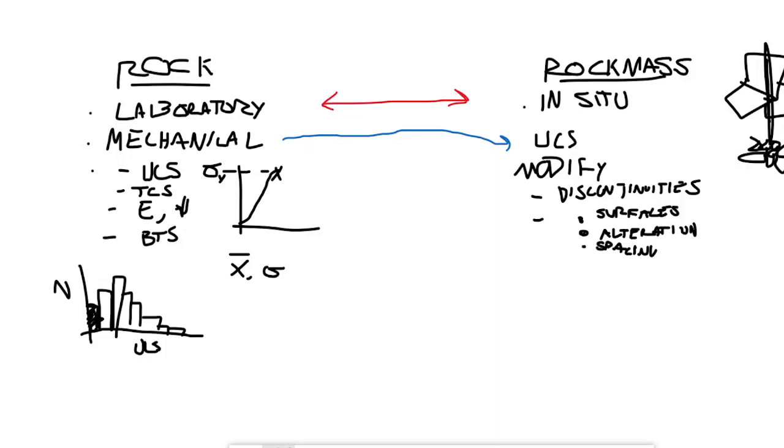And again, I'm just using the tunneling example here because it's kind of easy. But anytime you're dealing with in situ rock masses, this is going to come into play. Surface, underground excavations, doesn't matter, right? So all of that has to be considered. Groundwater, GW, our good friend. Water is good for life, but almost never good for underground workings. You have to deal with it, you have to pump it, and of course it weakens the rock itself. It makes it more slick and ready for shear failure.